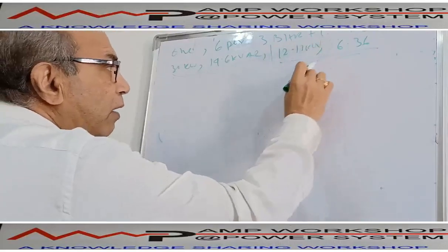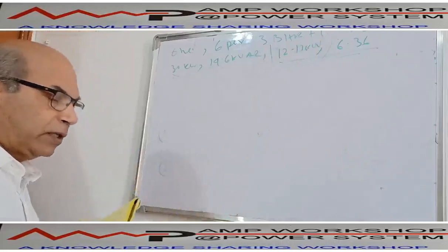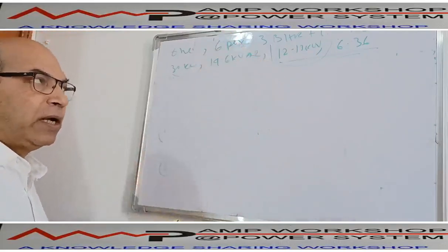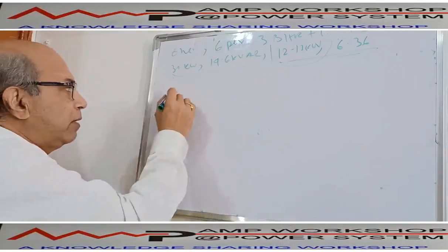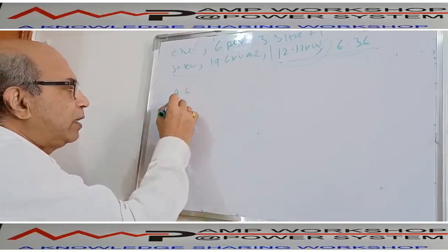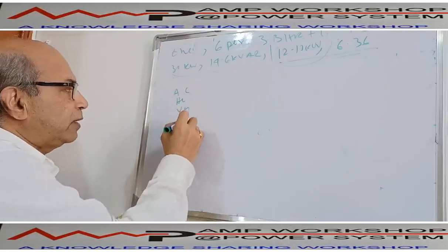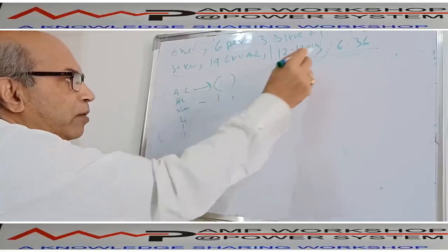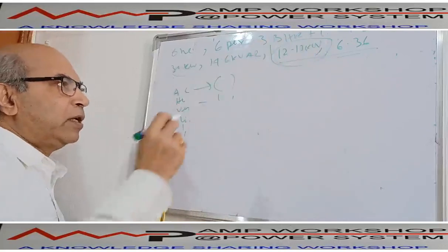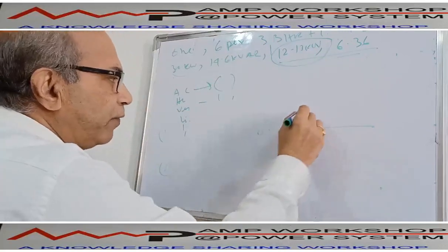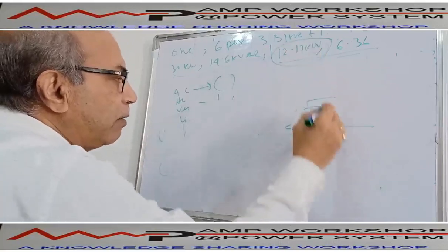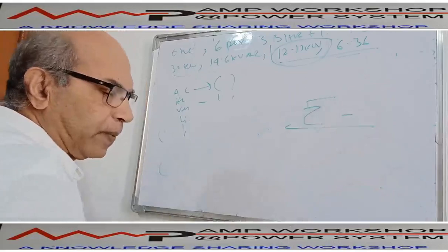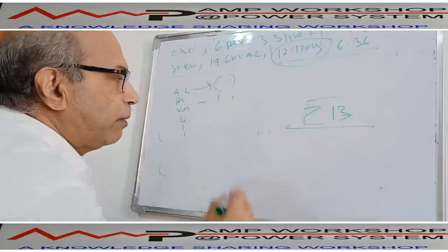This kilowatt which I got, 12.13 kilowatt running, comes from summing all the individual loads, okay. Now what are the individual systems? We have the AC system, heating system, ventilation system, lighting system, all these subsystems. Each has a maximum demand. On summing all the maximum demands, we have got 12 to 13 kilowatt. So 13 kilowatt is the sum of the maximum demand.